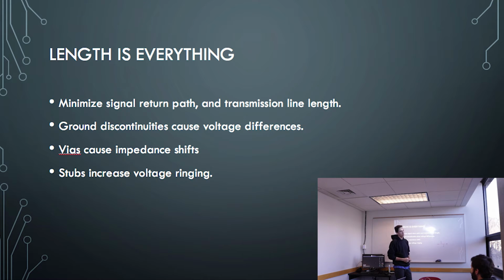That's a big one. Keeping lines short for any data communication protocol is going to be a big thing when it comes to board designing. So when you're thinking about designing, say, our next board, we want to keep the lines as short as possible, and usually you want to keep the UART TX and UART RX matched, just for simplicity reasons.